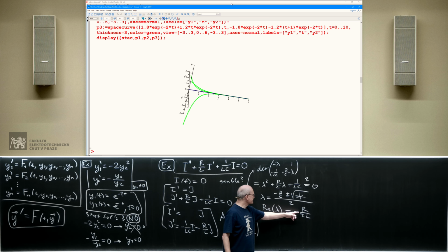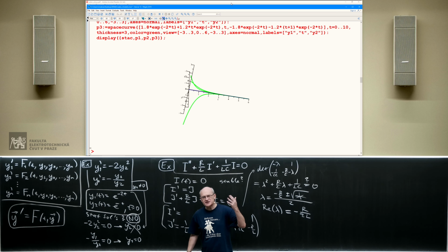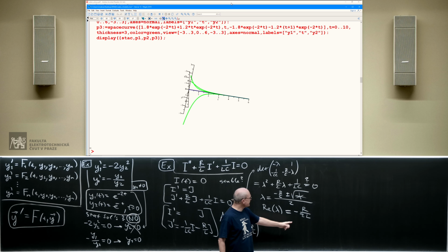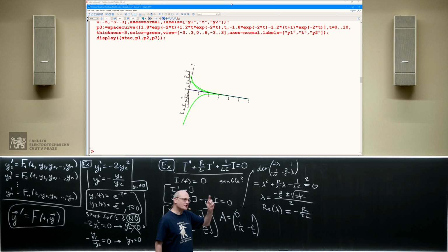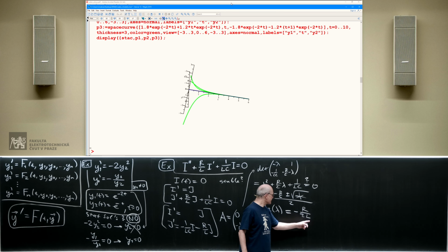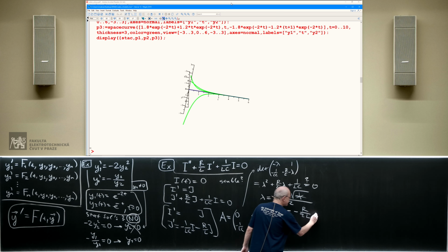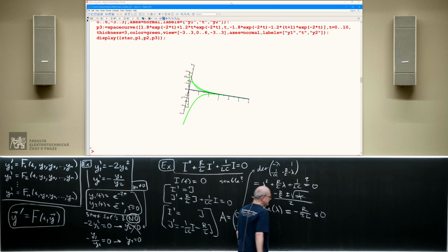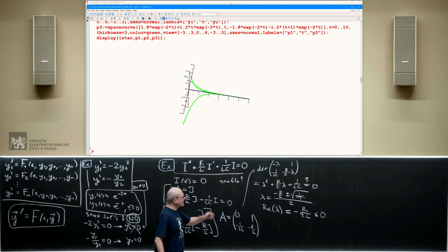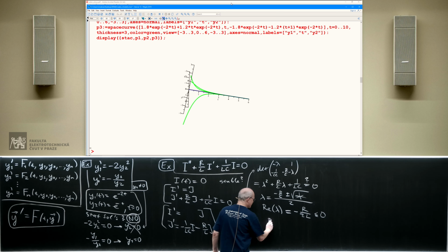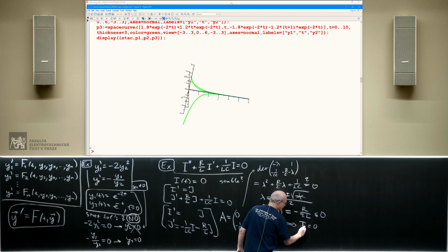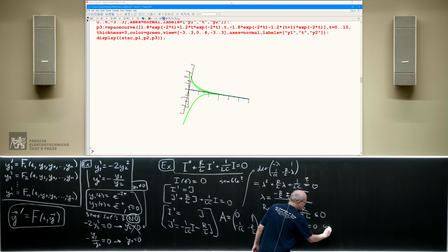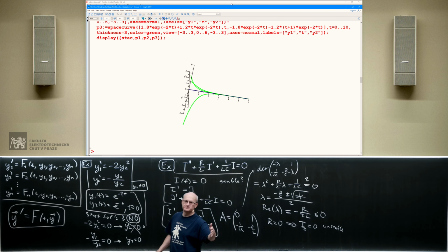Now R is the resistance or whatever. These are physical constants. The important thing is they can never be negative. They are both positive, R and L, or perhaps 0 for R. So I know for sure that this is less than or equal to 0. And now there are two distinct cases. When R is 0, then the trivial solution is unstable. So the current can flow indefinitely.